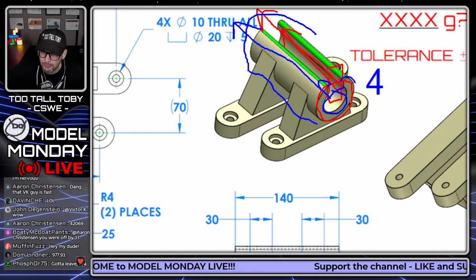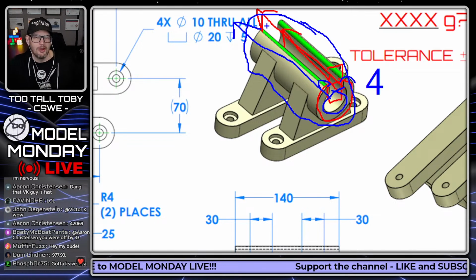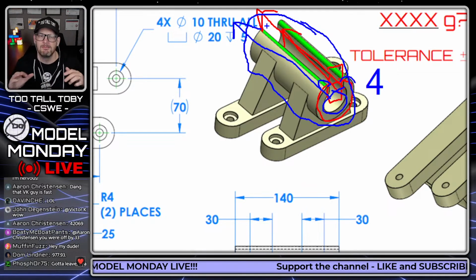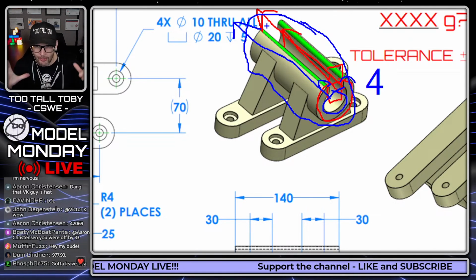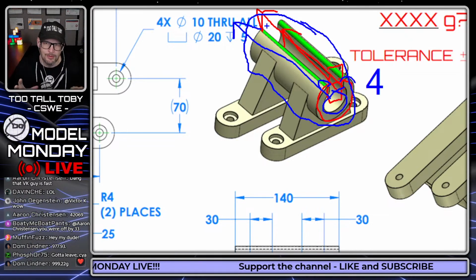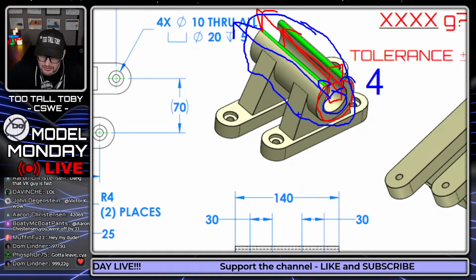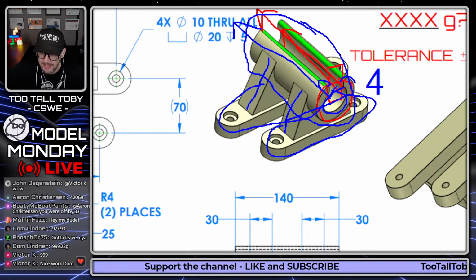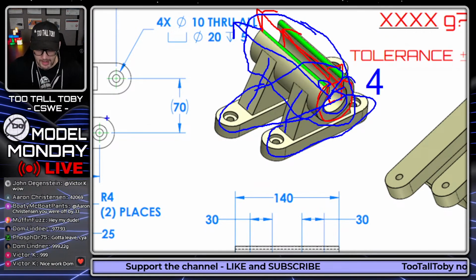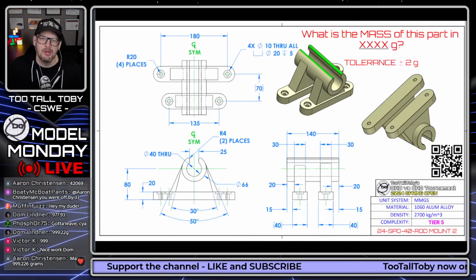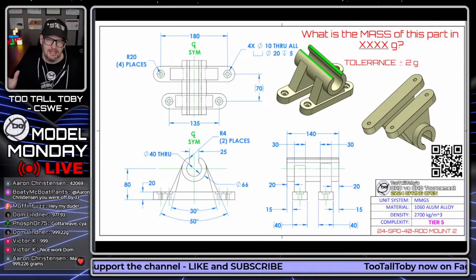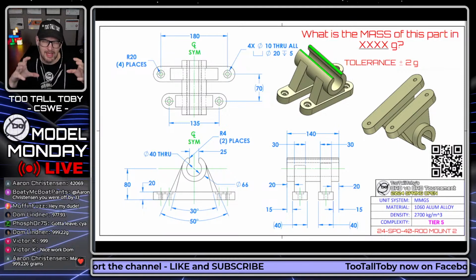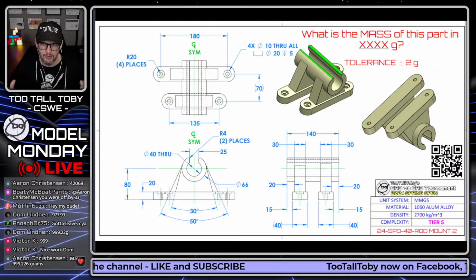And you might call this region of the model the upper sleeve. So instead of looking at the entire model in its entirety, you could look at it in different sections and kind of model through those different sections. So you've got this upper sleeve section, you've got this angled support section 1, you've got this lower base section 1, you've got this angled support section 2, you've got this lower base section 2. This is what you want to do whenever you're going from a 2D print to a 3D model. You want to discretize the model. You want to think about the model in different sections rather than imagining the entire model all at once.